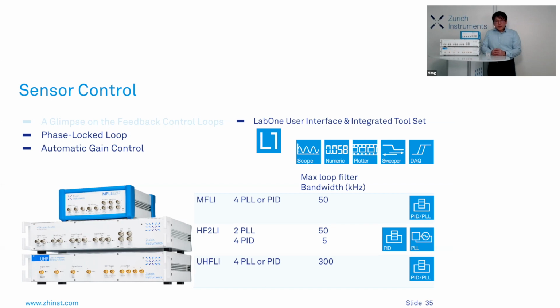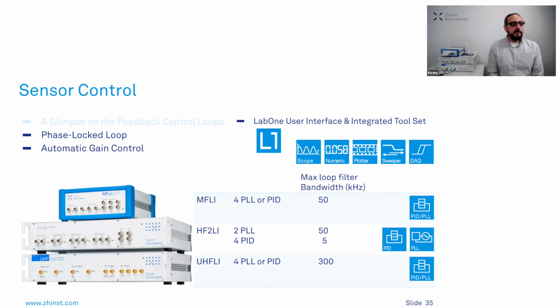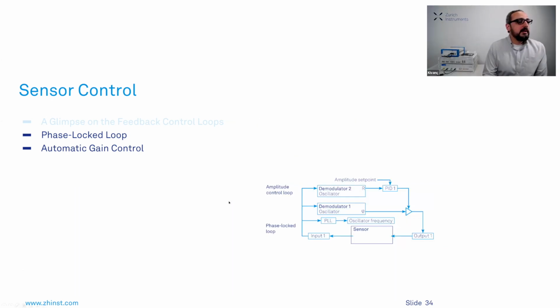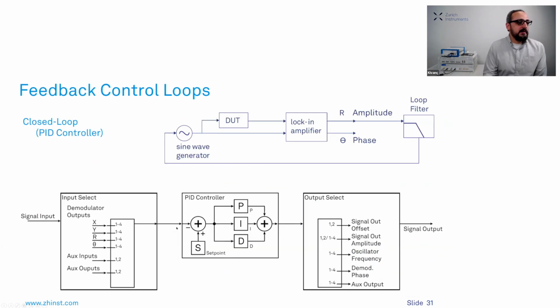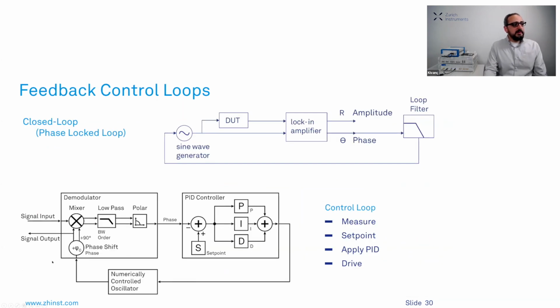And a related question to it is, an attendee asked, how is the bandwidth in your PID and PLL related to the feedback speed or rate? Of course, and then I can grab this slide here. So again, we do the measurement with the lock-in, right? So in the lock-in measurement, we demodulate the incoming signal. And the filter bandwidth we are talking about is the response of this whole system that I'm showing you. But we also have a low pass filter in the measurement process as well.